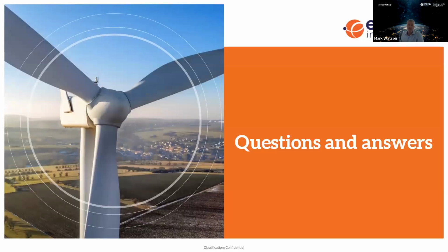For high voltage service, we have tasks which sit both sides of the boundary. Currently, this work is managed under an AWP with the HV isolations agreed by the AP. How would you recommend we proceed based on each scenario described? Should this be an isolation certificate with a CIC?